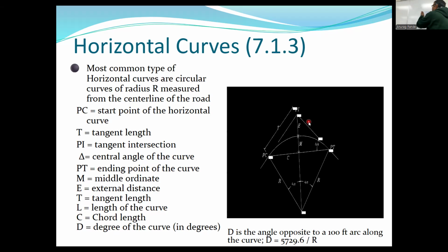But if you didn't have something like a T intersection, and there was a hill or whatever, you're just trying to change this direction. Maybe there is a water body, and you're trying to get people from here to here. In some cases, that change of direction has to be achieved using what we call high-speed turns, and that is your horizontal curve. So these horizontal curves are drawn like this, and in this case, these are circular curves. So these arcs are circular curves.